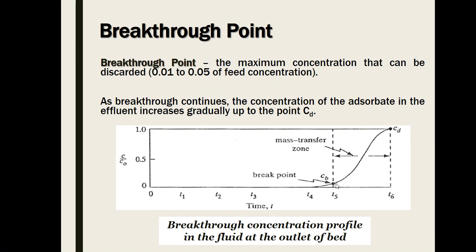Although until time t sub 6 in the illustration, there would still be an uptake. There will be an increase in the amount of solute in the fluid because some of the solute that already adhered on your adsorbent surface re-emerge. So the term that was used is re-emerge, meaning it loosened up from the surface because the surface is already saturated and it mixed with the remaining in your solution.